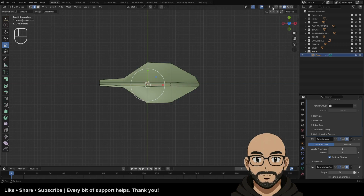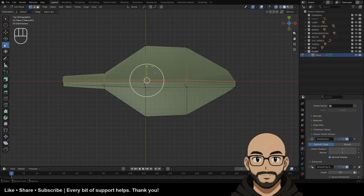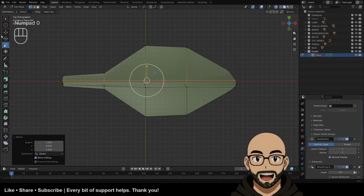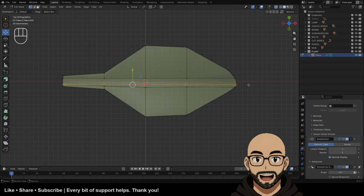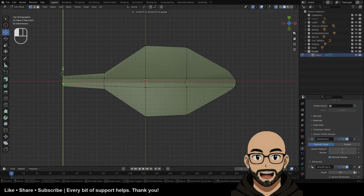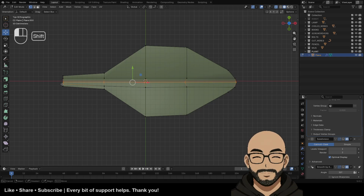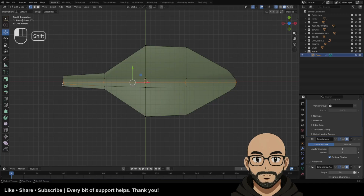Let's go to X-ray. Let's just line this up. So we're going to select all these vertices. I'm going to hit 0. That's lined up, and I'll just push this out. I'm going to select this center one. I'm going to select this outer one here and move this out of the way. So I'll select all of these. Shift deselect this.